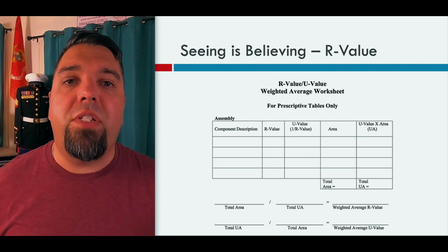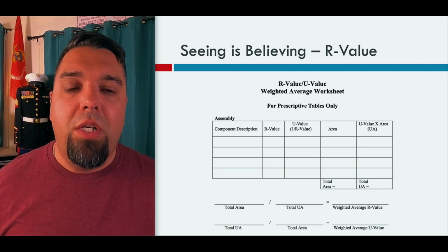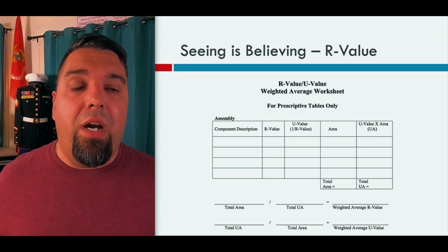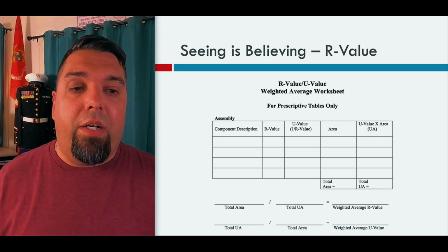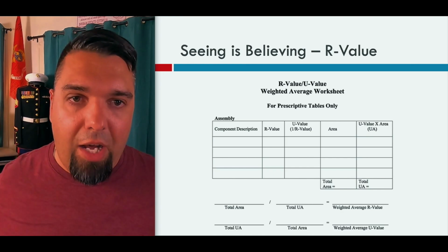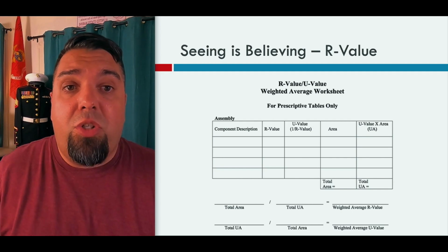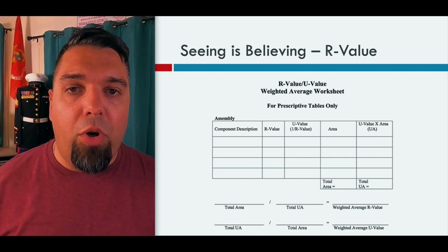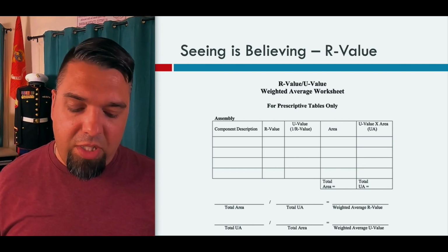And I'm going to show you how this starts to impact your load calculation. It can get pretty drastic if you have large ceilings. Let's say a colonial style home with just one large ceiling across, or a ranch style house where as much as 25% of your heat loss is your ceiling. So really important, you take into account all of the components.